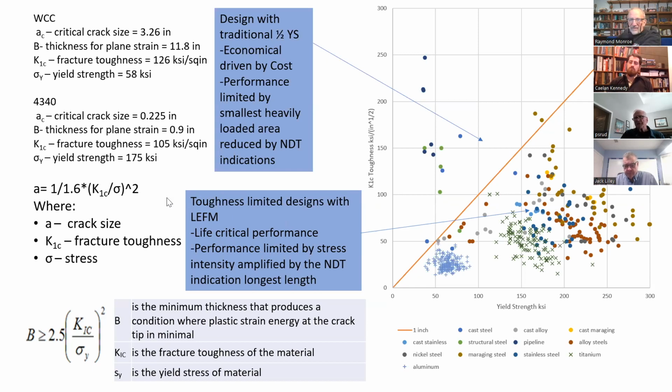Yeah. Well, one thing I can say is that, if you get to the point where you're going to use fracture toughness data, you've got a lot of teaching to do to engineers. Yes. Because it's been my feeling, and what I've seen is, we did some work on one particular part. We were worried about critical flaw size, and so we did some K1C testing and found out, lo and behold, the critical flaw size was 3/4 of an inch. Oh, yeah. Yeah, so you can say that, but when you say that to an engineer, he just shakes his head.